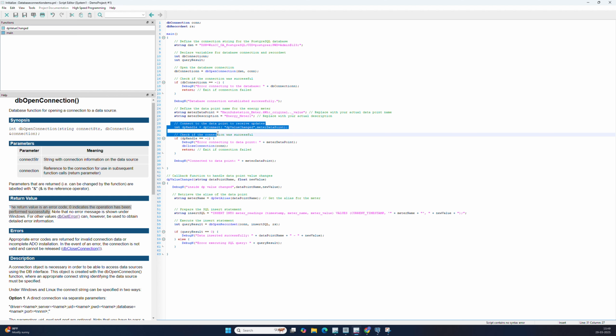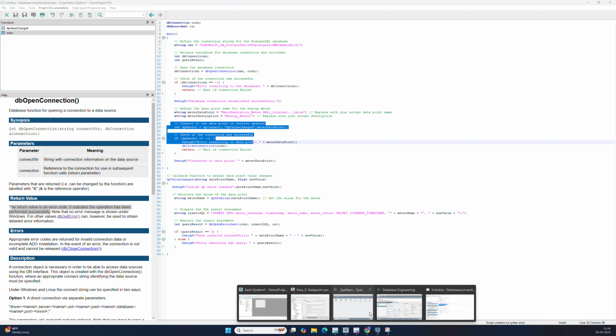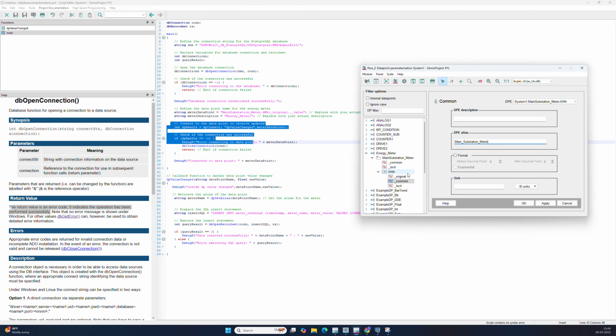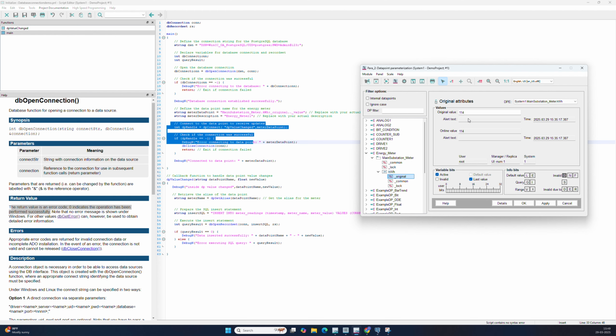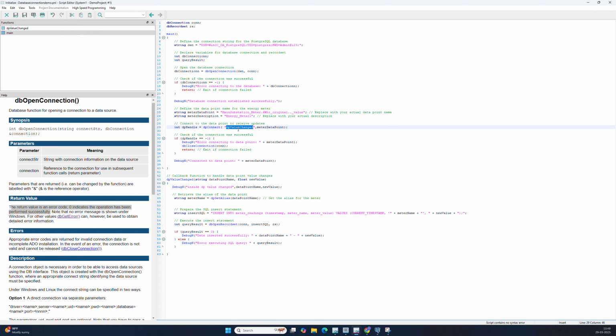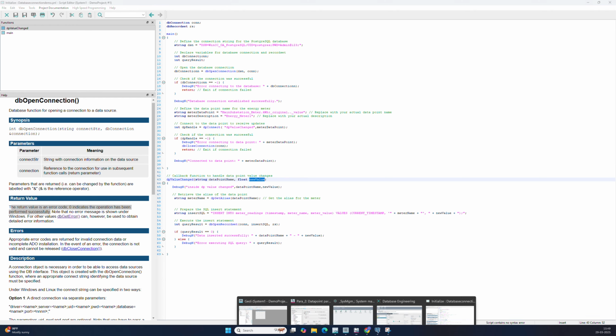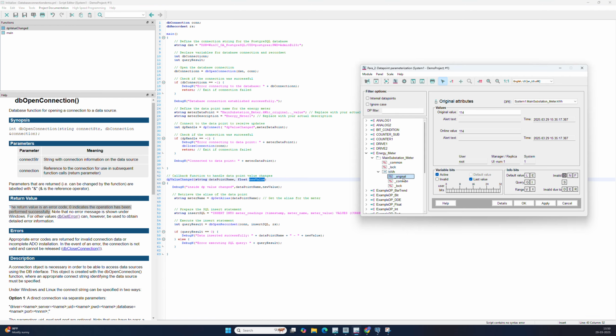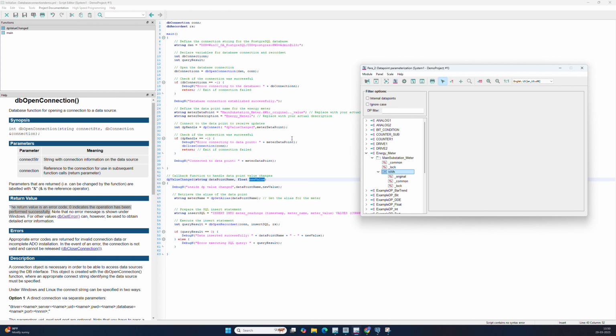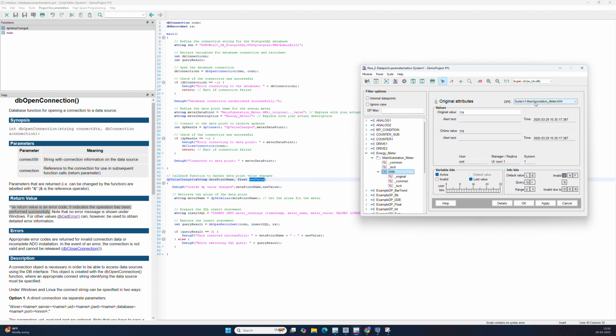Now here, see how to communicate with that particular data point, right? We need to fetch the live values which are being changed in this one. So using a dpConnect function, I'm connecting with the meter data point. That is, I'm connecting to this tag value. Once this tag value is changed, the value will be passed to the value change function here. Here we will get the tag name. Here we will get the value, right? So here we can observe I'm passing the value from this particular tag name. The tag name is this one, main substation meter dot kWh.